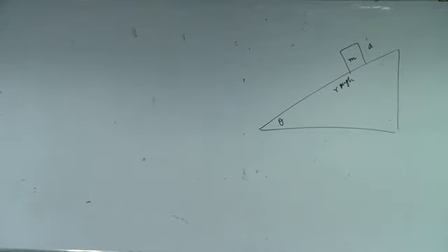Yes. Excellent. Absolutely. And how much would be the torque of friction? Think and say. Torque: mg sin theta into a by 2. Correct. Now find out at what distance from the center the normal force is acting.